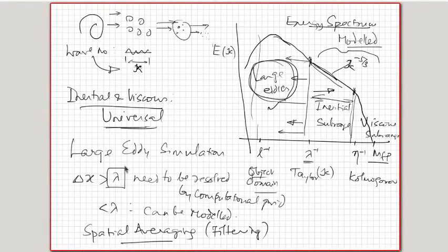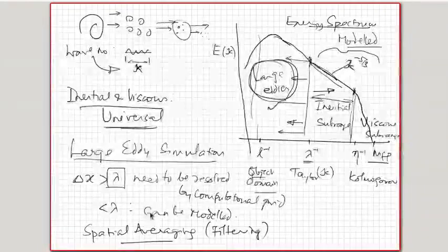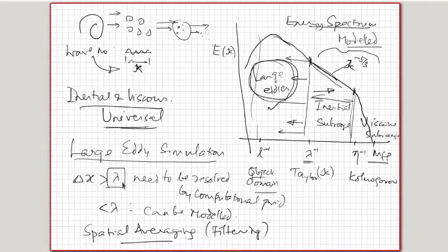So then you solve them using the partial differential equations, and whatever is happening inside the grid, the terms that come because of filtering, just like the Reynolds stress terms that you get in your time averaging, you will get the filtered terms, the u prime, v prime terms which are filtered out.